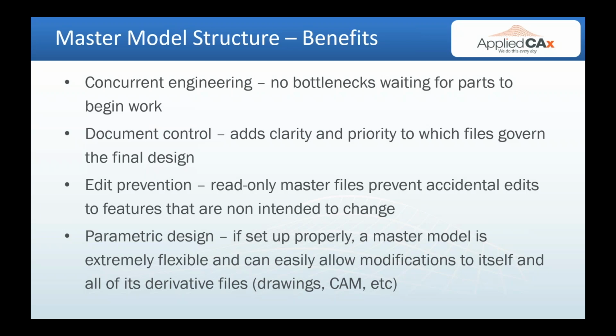So if you are a prototype programmer, you'll feel comfortable using this approach, creating the correct final geometry if you're programming parts and making prototypes. And also, if you're a proficient enough designer, you can take huge advantage of how parametric and associative NX is. So you can make very flexible models that update very easily if you set up your master models correctly. You can change a dimension and have your drawing and CAM file update without any major issues. So if you set up your master model structure correctly, you get a lot of time-saving benefits.